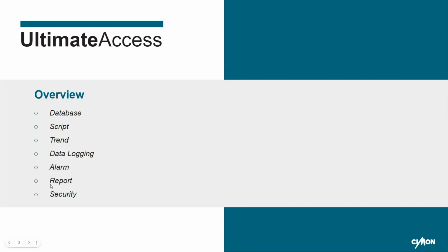And then we have reporting. So reporting is a next level to historian. It takes the historical data, crunches the numbers, computes analysis, right? And then it generates a glorified data sheet that you can print out so someone can look at it, or you can just store it historically for yourself as well. So it's like a top tier historian feature that's not typically offered in your HMI software.